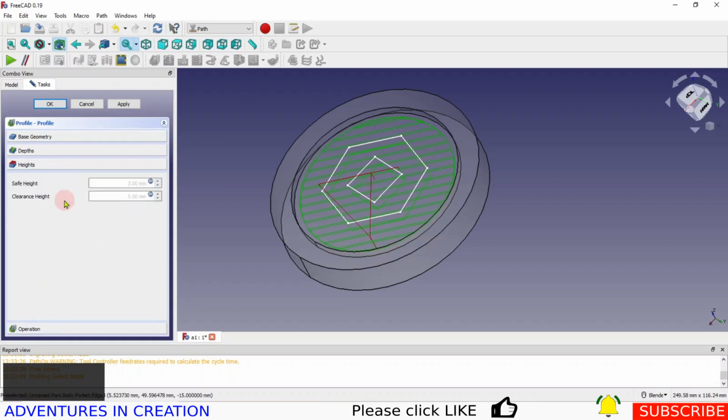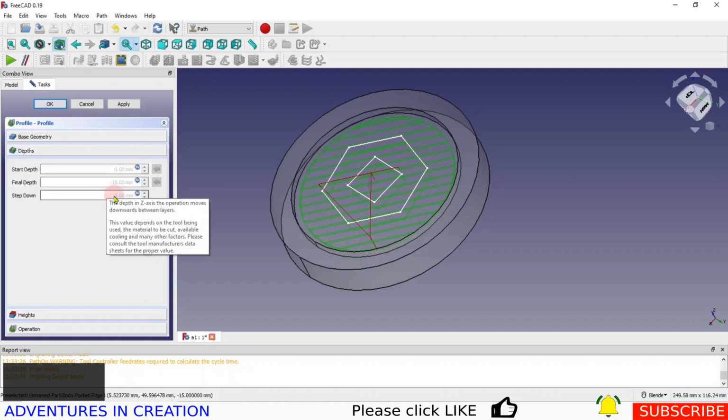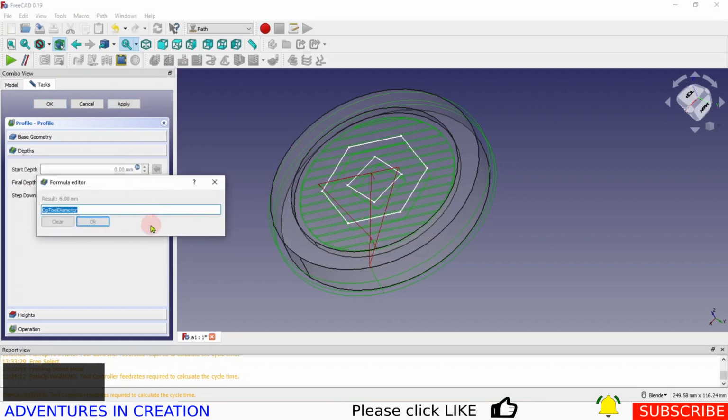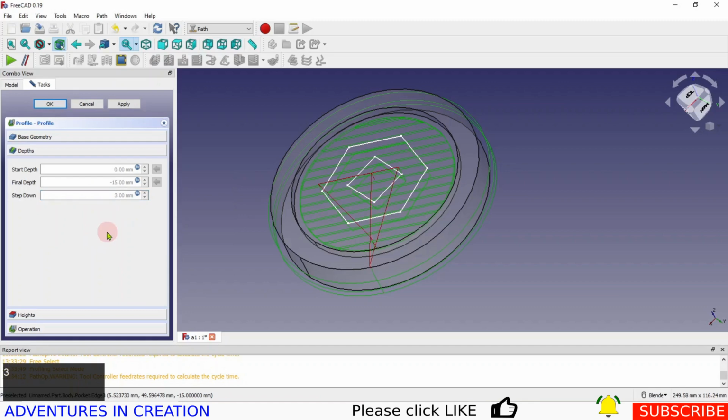And this time we're going to check on our height. So again, the 5 and the 3 are perfect, and -15 and 0, that's perfect. Step downs of 3. Now, because we changed the tool, it's actually going to change that to 6 because it will be the dimension of the tool. So we're going to be a little bit careful for that. You see that change when I hit apply? So we're going to change that to 3 because I do actually want it to step down 3.